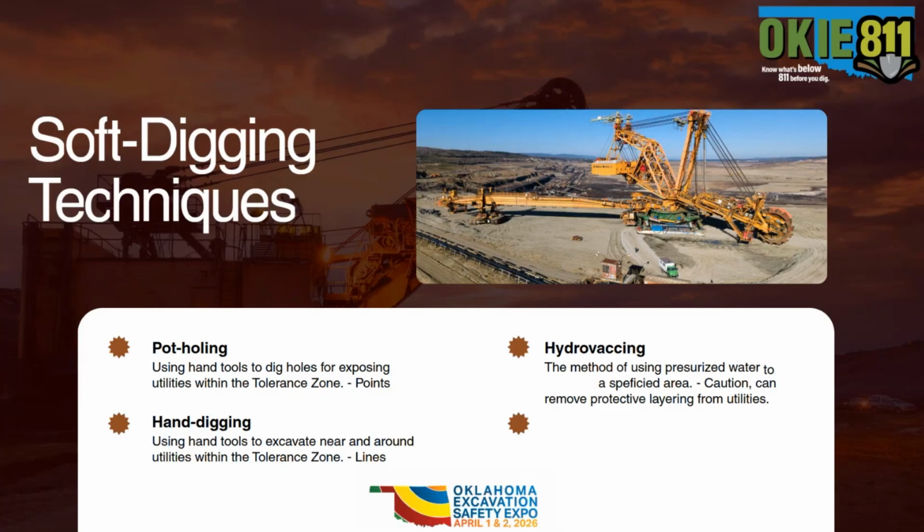Hydrovacking, which is coming up onto the scene, it's becoming quite a new shining method. It's a method that uses pressurized water to excavate a specific area. Now, it is important to exercise caution with using hydrovacking, as it can strip certain utilities of their protective coatings. And so it's always good to double check with the utility operators what is going to be a good practice there, or anyone who has the hydrovacking systems.